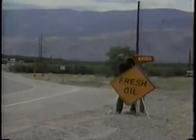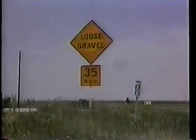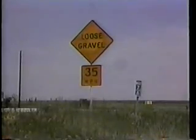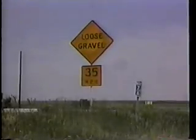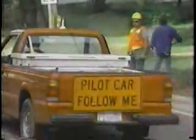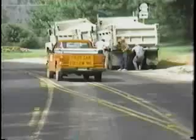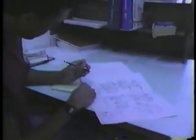So most agencies require fresh oil and loose gravel signs on both ends of the work area. That way, motorists are warned to use caution when driving over new chip seals. On long jobs, advisory speed signs should also be placed every 2 kilometers or so. To further protect motorists and the new chip seal, pilot cars may be needed on projects constructed under traffic. So carefully review the traffic control plan, make sure it's approved, and see that it's followed throughout construction.